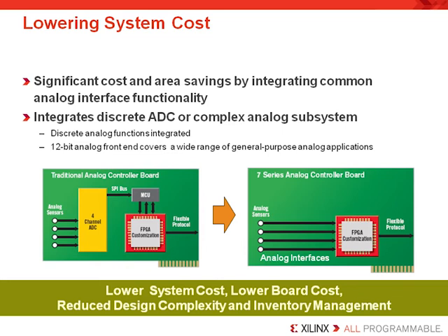Now let's look at the following figure, which illustrates a simple controller board that includes a 4-channel analog to digital converter, a small microcontroller, as well as an FPGA. Whether it is a motor control or an energy management system, typically there is a DSP or microcontroller unit which performs the housekeeping functions. The discrete ADC performs an analog to digital conversion of the input signal for the MCU to process. Sometimes the analog to digital converter is integrated into the DSP or the MCU device.